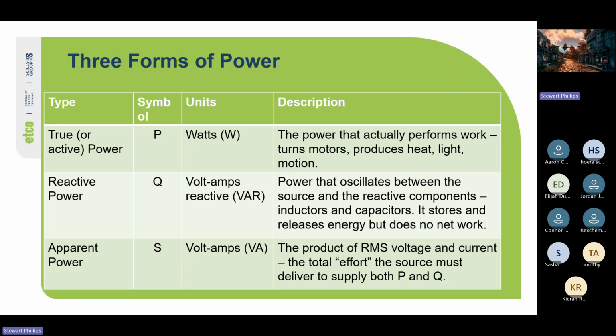And the reason we measure apparent power in volt amps is because it's the total voltage and current measured. So it's the total power supplied. It's why we usually rate transformers in kVA or VA, because it is the total effort that the transformer can supply. Because we cannot guarantee what the power factor or the reactive power of the load we're supplying with that transformer is actually going to use. So therefore we measure our transformer in VA.